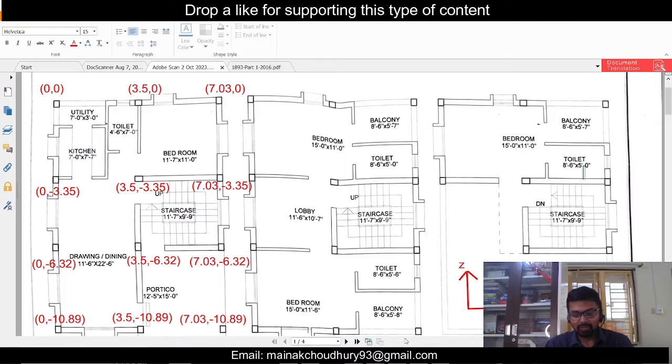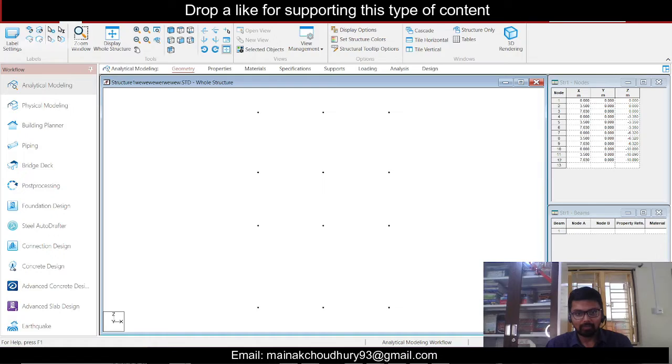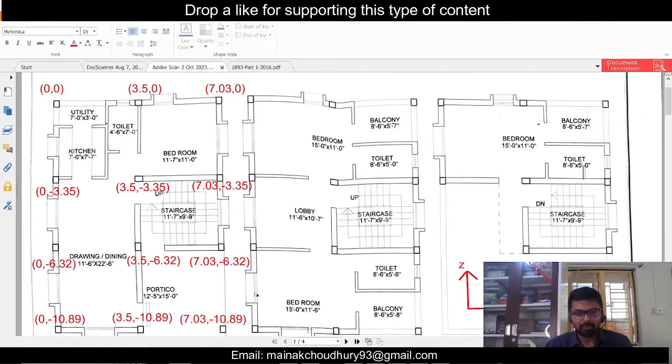Okay, so let's insert the coordinates one by one into STAAD Pro. And remember, the y coordinate is the height. If you consider the plinth level at 0, then y will be 0. So let's consider the plinth level at 0 and insert all the coordinates one by one. Okay, as you can see, the coordinates have been inserted. You can match with this plan just to see whether everything is okay or not.